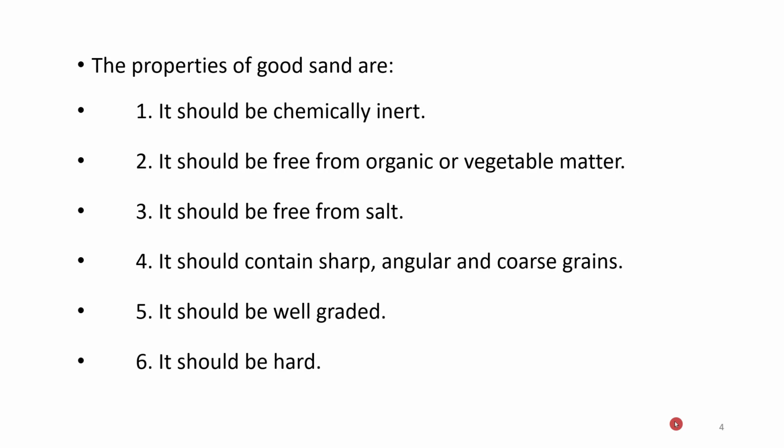The various properties of good sand that is to be used in mortar are: the sand should be chemically inert. In the mortar or even in concrete, the sand should not react with the cement. It is just a filling material, so it should not react chemically with the components of the concrete or even mortar. It should be free from organic and vegetable matters which will affect the behavior of the cement mortar.